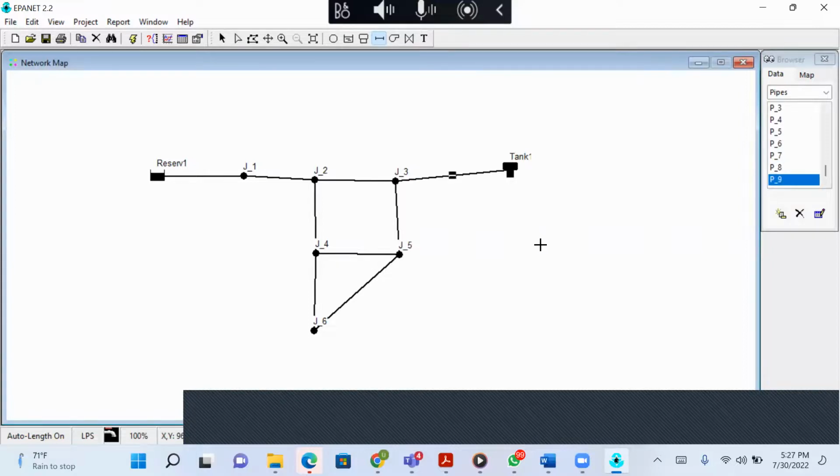You can see I have drawn it. So if I want to do that curvature that you saw there, I use a vertex. So if I come here, I click on vertex, I'll say add vertex. I'll click on it again. I'll say add vertex. One vertex will appear. If you do it the first time, you don't see anything, but if you do it again and again, they will appear. So I think three vertices is enough for me to draw a curve.